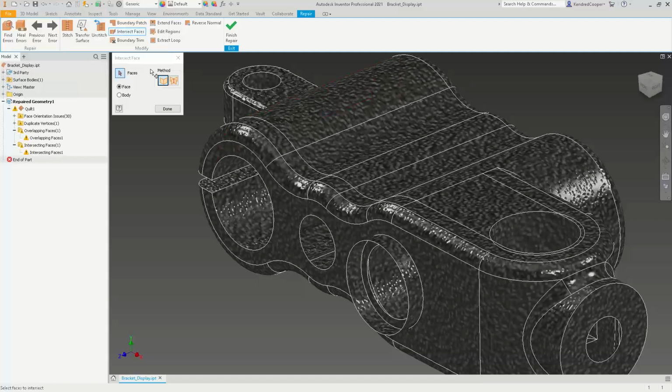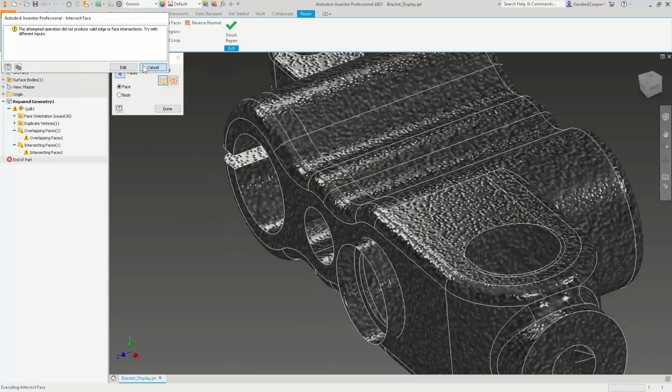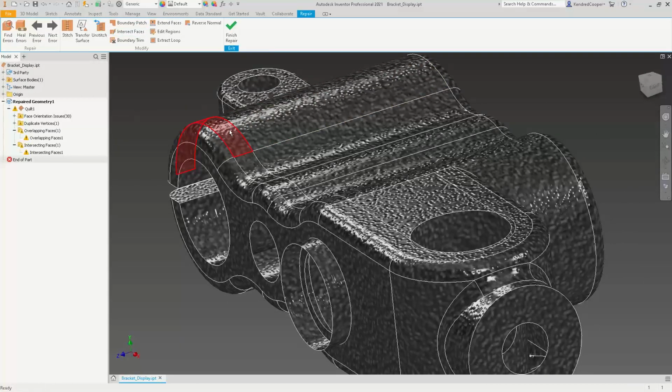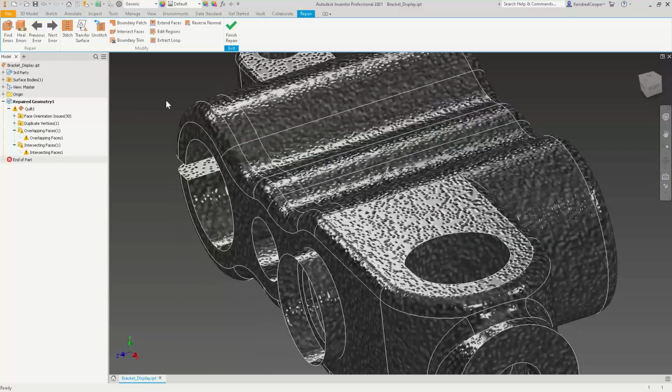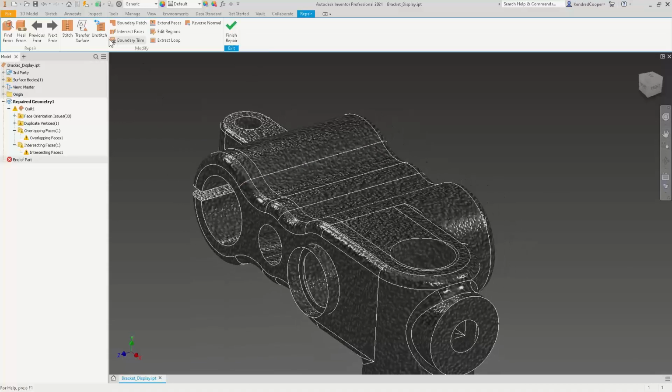Sometimes you're going to run into issues if you select them in the backwards format or if they're not even overlapping, because that's one thing I did when I stitched it. It pulled the overlaps out. It got rid of that overlapping issue. So now we're just looking at two faces right here instead of this longer face being underneath the shorter one. So coming in here and running an unstitch or running a stitch can automatically, if you will, solve a lot of those issues.